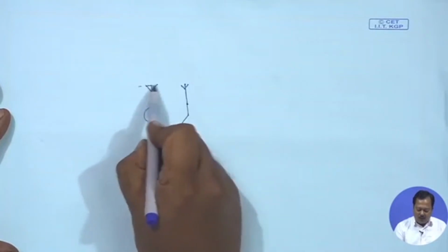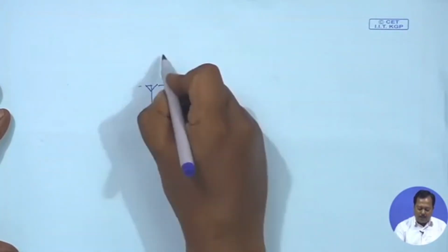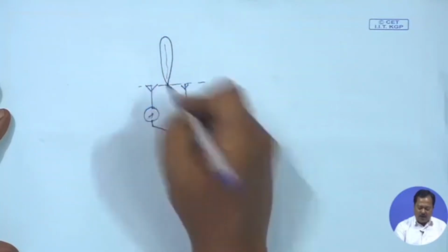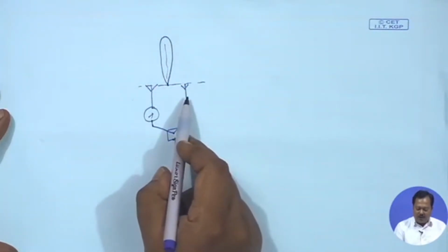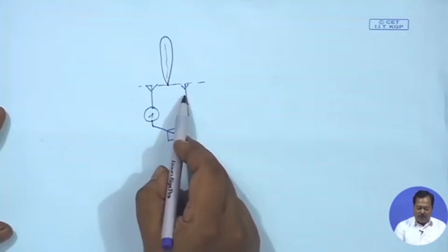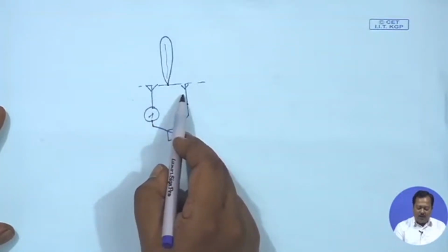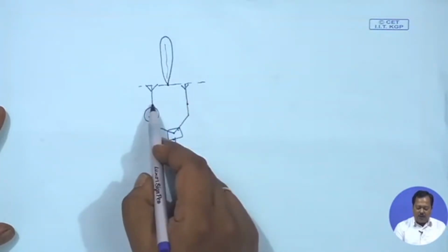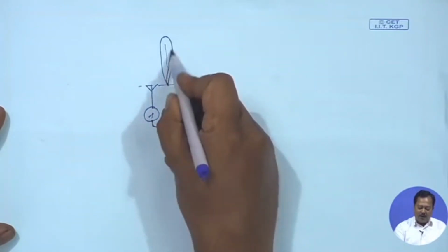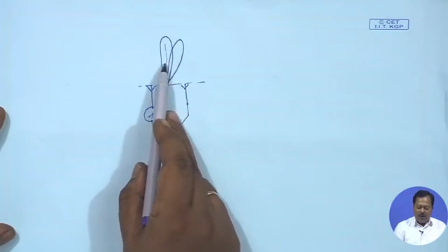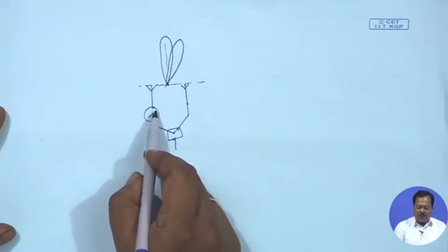Now, the resultant beam direction is in broadside direction when the phase difference between two antenna feeds is 0. Now, if we introduce a phase shift between these two antennas, then the beam direction will change, and this new beam direction depends on the phase shift value.